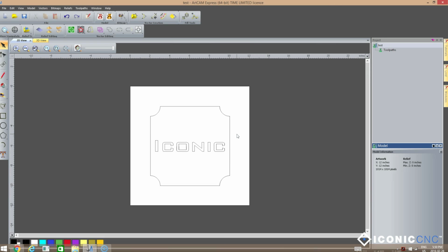All right, the last step in this process is we're now going to create the toolpath. So essentially we've created our project, our design side of our project, which is the rectangle and the text. And now we're going to go over here to click on the Toolpaths tool.